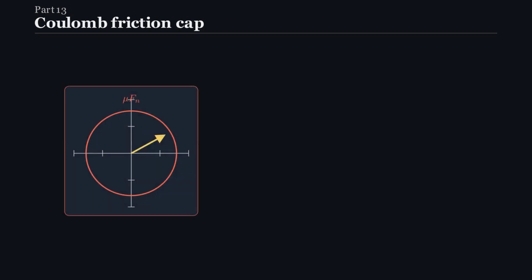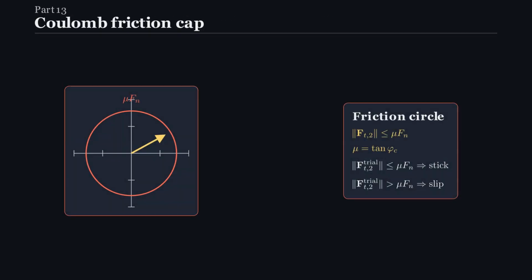The tangential force cannot grow indefinitely. Its magnitude is capped by the microscopic interparticle friction coefficient times the normal force. Equivalently, the coefficient is the tangent of the contact friction angle. This contact friction angle is not automatically the macroscopic friction angle of the granular assembly.